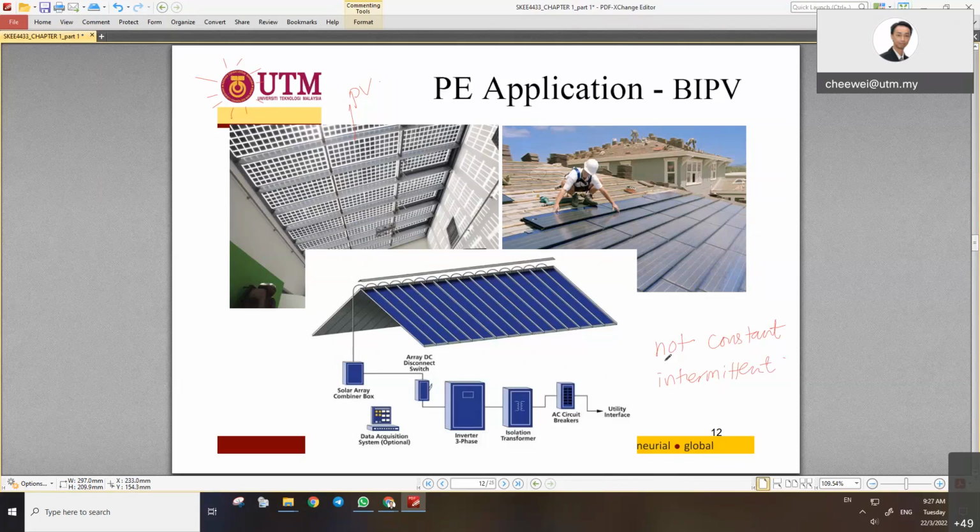And then it fluctuates, because of clouds. The clouds move from A to B. Oh, it shades. So you have shadings, meaning what? No supply, no output. Okay, all these are the natural characteristics of renewable energy. For example, PV, what about wind? Wind is not blowing all the time, right? At the same speed. It also gives you the same condition. So if you have fluctuating inputs and you want the output to be constant, then you will need power electronics to do the job.